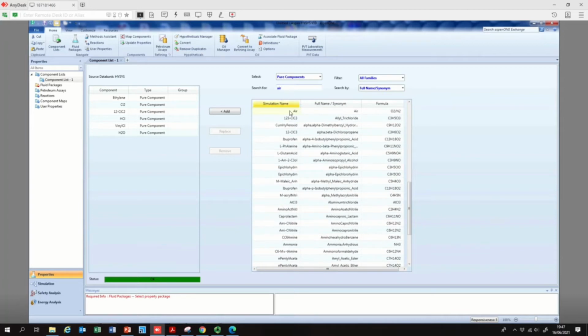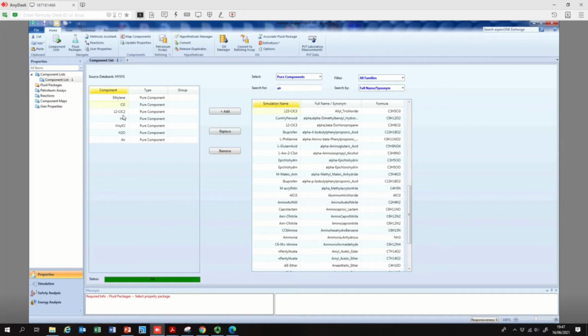Okay, just type air and then you can double click. So we have 7 components: ethylene, chlorine, ethylene dichloride, hydrochloric acid, vinyl chloride monomer, water, and air. Yeah? So we already added all the fluids. We can call them fluid components, or simply the component list. We have all the reactants and products involved in all the chemical reactions during the manufacturing of vinyl chloride monomer. So far good.